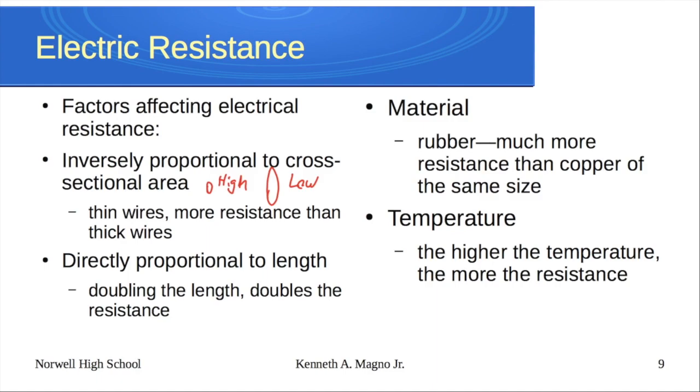So when you buy cheap electronics sometimes, I don't know if any of you ever bought a cheap USB wire or a charging wire for your iPhone, and you'll notice they sometimes break or burn out. Well, that's because they're made with thinner wire. It's cheaper, but it also can't handle the higher current values that are needed, and they can burn out or break because of that higher resistance, that higher amount of heat they generate.